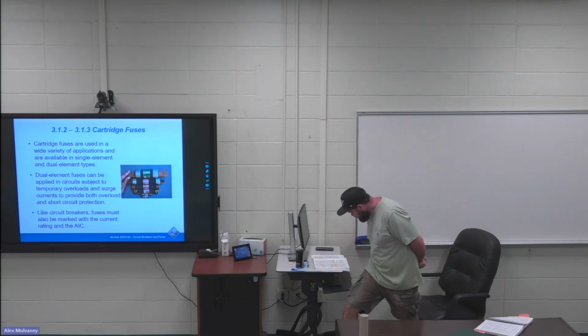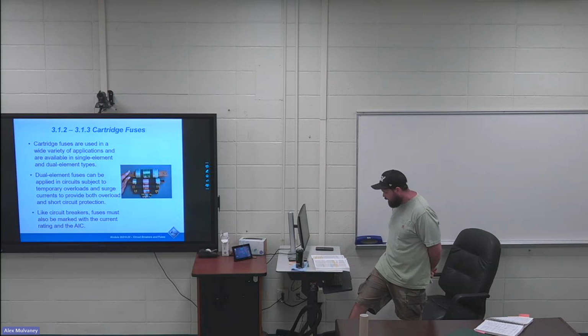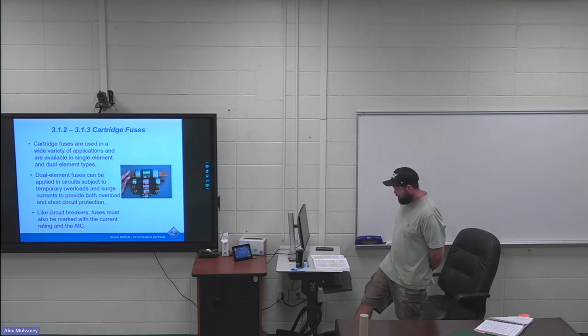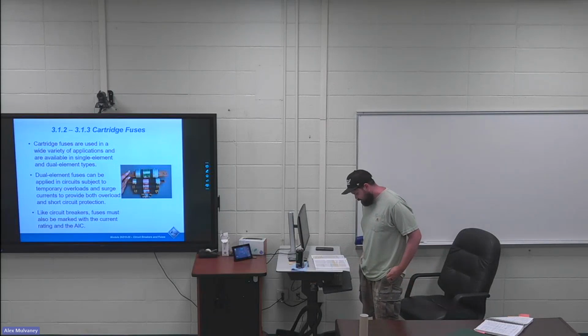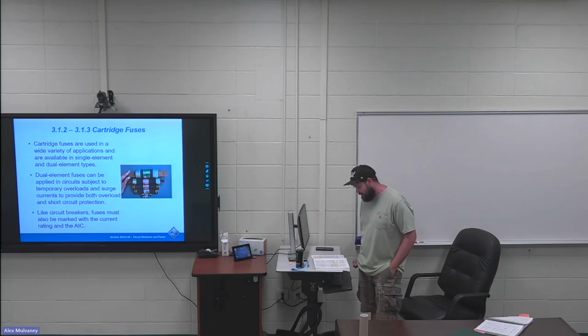Next paragraph, first sentence is highlighted. Dual element cartridge fuses. I highly recommend looking up videos. I think it's Eaton that does a pretty good video of a dual element cartridge fuse. Unlike single element fuses, the dual element fuse can be applied in circuits subject to temporary motor overload and surge currents to provide both high performance short circuit and overload protection.